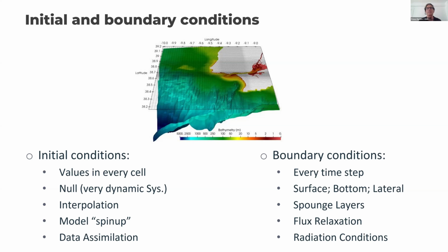Start with zero velocities everywhere. In the ocean, no. If you were trying to start a model for the entire Atlantic with zero velocities everywhere, you would need to run it for, I don't know, more than 1 century to get real velocities. So it's not feasible to do that. In that case, in very large, less dynamic systems, what we do is start by using climatological averages. We start from the climatological averages, and we also do a spin-up process in order to get the real results, okay?